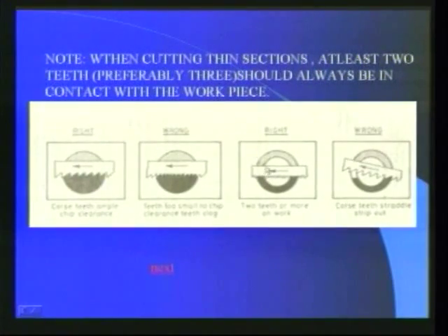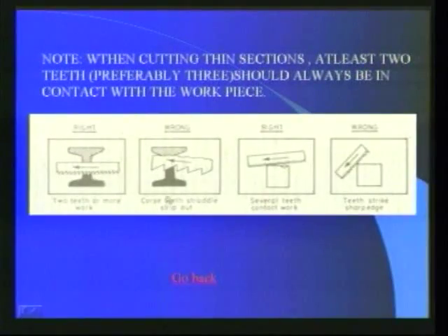Here, for cutting tubes, fine pitch tooth is used. It is the right method because 2 or 3 teeth are in contact with the work. If we use coarse teeth blade, there is a chance to strip out. We will see some other applications.